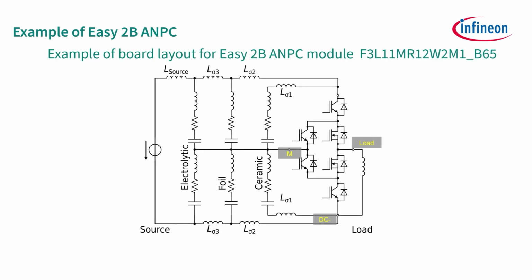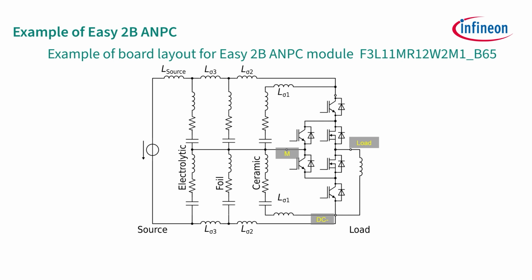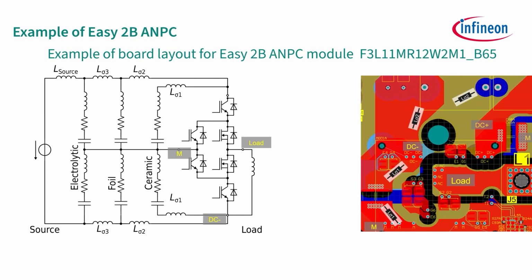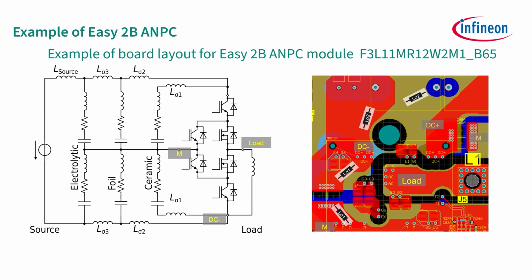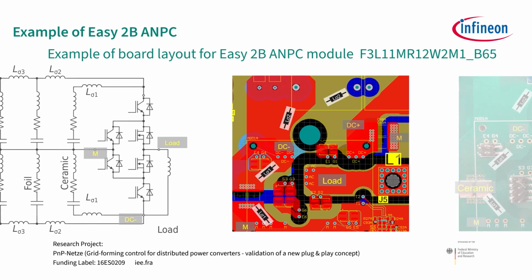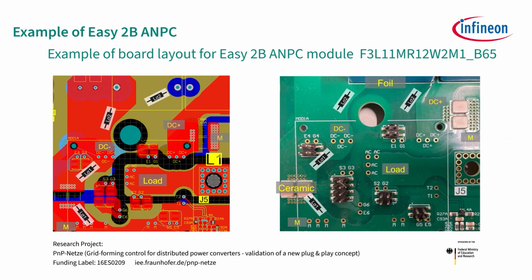Utilizing a multi-layer PCB is recommended to facilitate a low inductance connection of the capacitors to the EZ module. Employing a setup involving a direct connection of the ceramic capacitors to the DC pins has proven to be an advantage. When using the press-in device for the EZ module, it is essential to take precautions to minimize stress on the ceramic capacitors to prevent any potential damage.